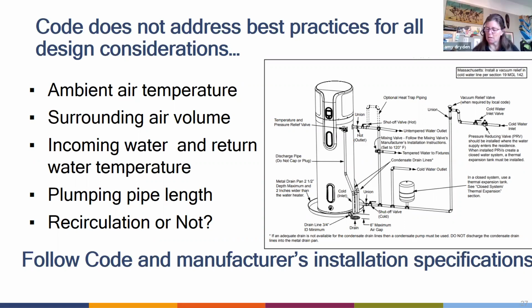The only thing, two things I wanted to add. Just one on the condensate. I'll talk about it again later, but it's water, right? It's just water condensing on the unit and being drained out, unlike AC condensate, right? So it's not condensate from a combustion appliance where you have a different treatment of it. So it's just water.